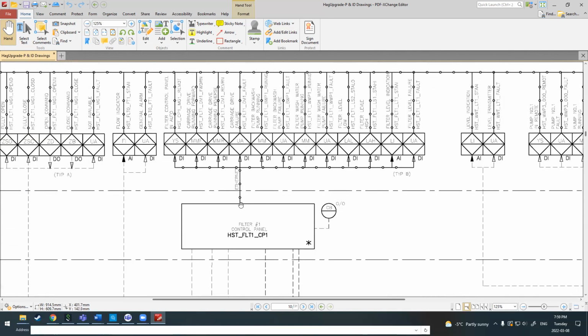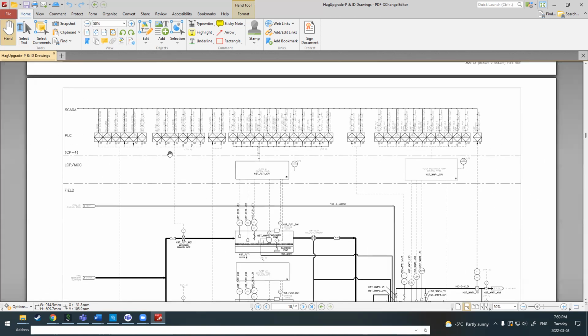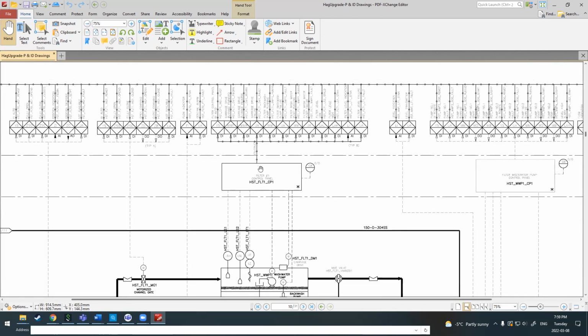And then you can see here, this says Ethernet. So this connection back to SCADA is not hardwired. There's an Ethernet connection back to another PLC. So you need to watch for that. Sometimes you might have Modbus, you might have TCP/IP Modbus, RTU Modbus, Ethernet IP, CIP protocol, any number of things. They can throw curveballs at you on these P&IDs.